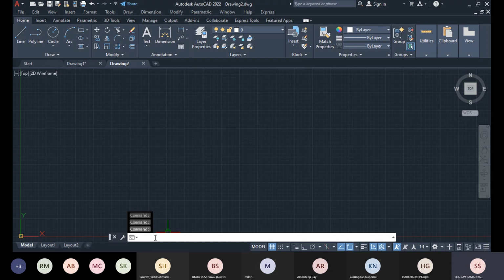There is a command that can guide you about the exact dimension of your page. It is essential that whenever you start a drawing on an open page, you check the dimension of the page first, because if you don't, your drawing will not be perfect and you have to adjust a lot of parameters.